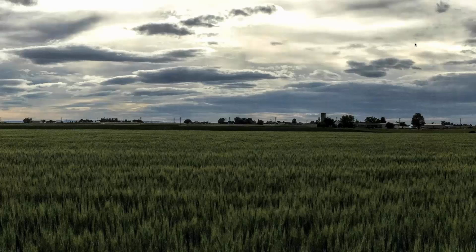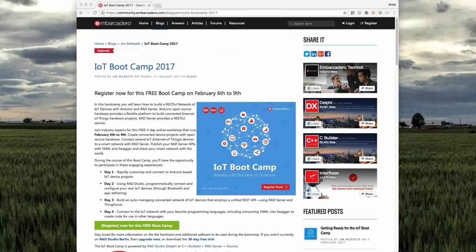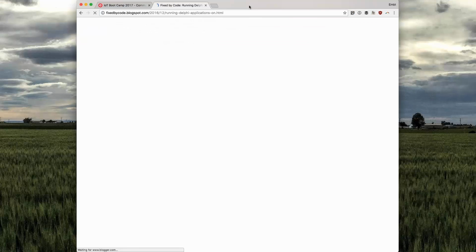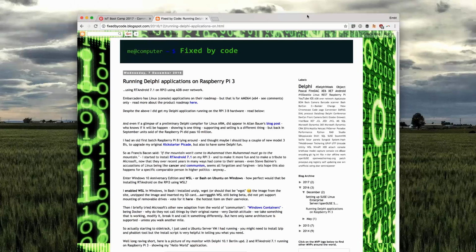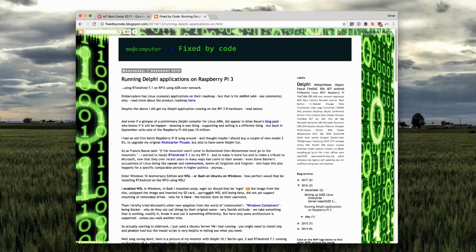But if I'm not mistaken, those controllers do have the capability to effectively lock the code and prevent reverse engineering it. On the other hand, if somebody wants to use expensive equipment and even read the content of the memory using, let's say, X-ray technology, well, then there is very little you can do about that. I mean, yeah, they can crack anything this way. There is nothing which is really absolutely safe. If somebody has X-ray and reads the content of the memory directly from the chip, even without powering it.